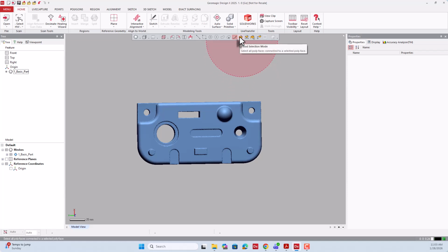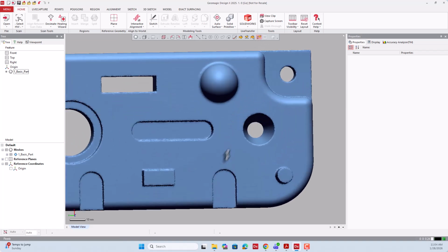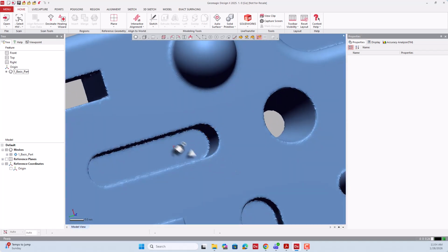And here we have a few other advanced selection modes. The main important item here is the Smart Selector tool, which you see in the very end here where my cursor is. This tool lets you select the triangles based on curvature. So you can zoom in, and let us say I want to select the bottom flat area. You can click on that flat area and hold the left mouse button and move your mouse. This will grow and expand your selection based on the curvature.